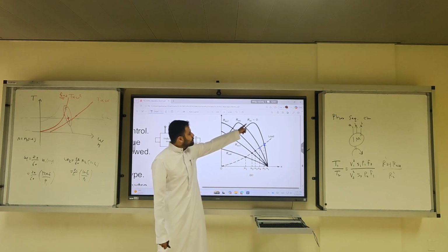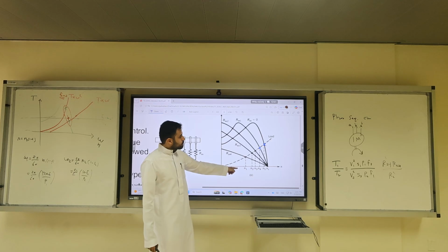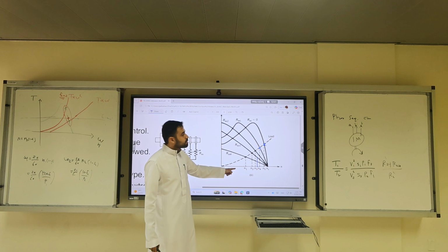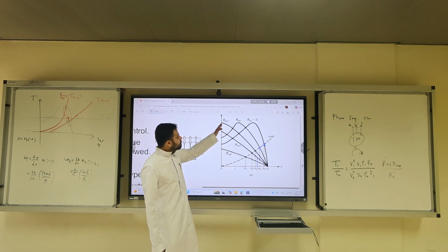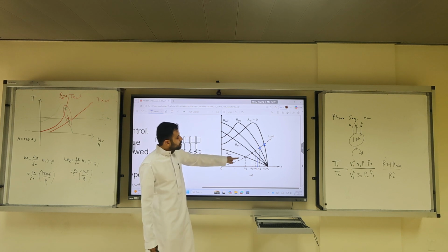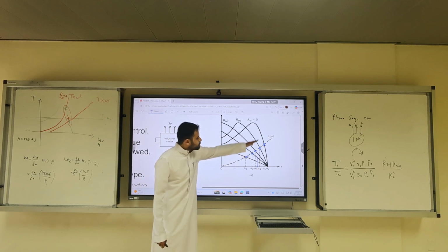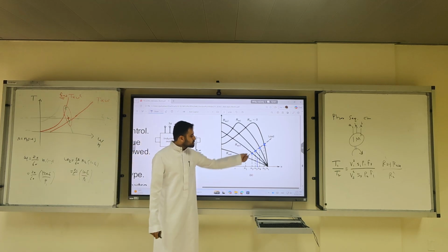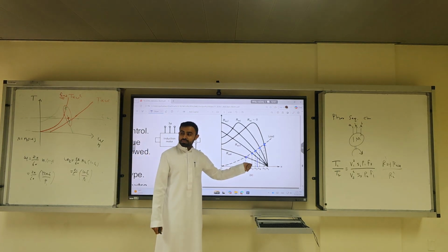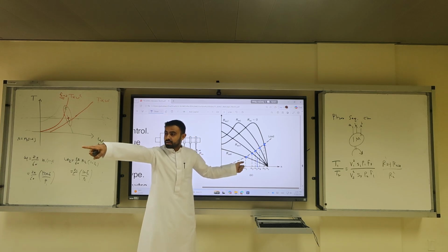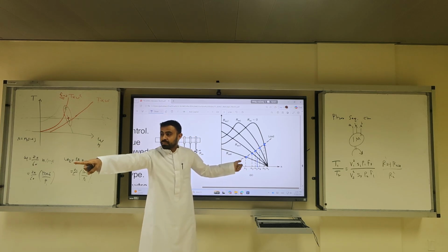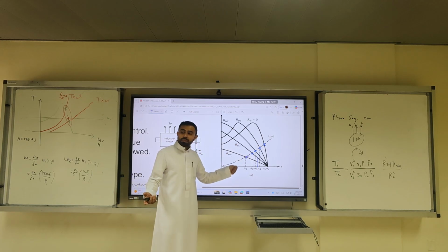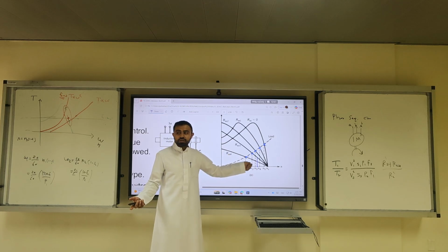Your maximum slip got shifted from slip at speed M4 to slip at speed somewhere here. For external 2, then we push the curve for 3 and 4, and we're operating always at lower torque. So if you add more resistance, you reduce the speed, but you still satisfy the load. So is there a problem if we're still satisfying the load? From the load perspective, we don't have a problem. The only problem is if my curves do not cross.